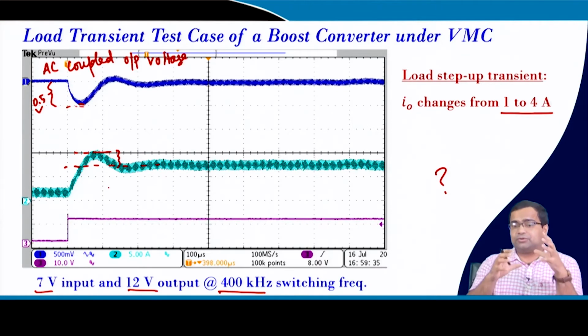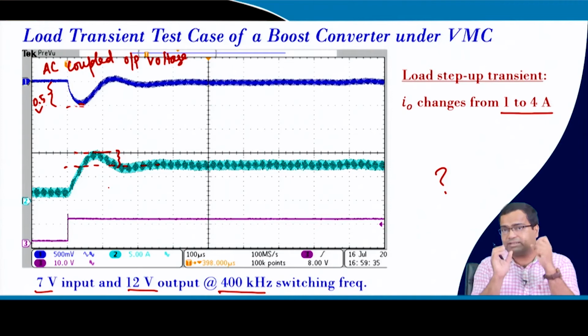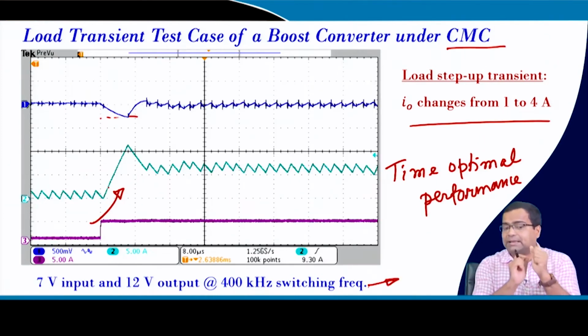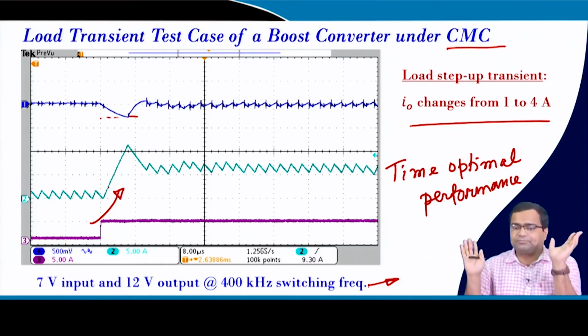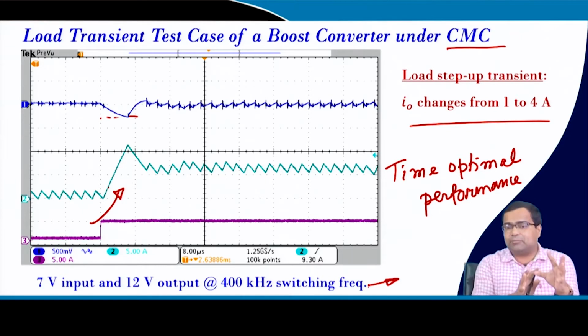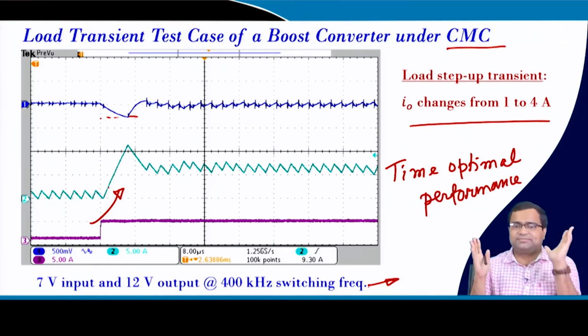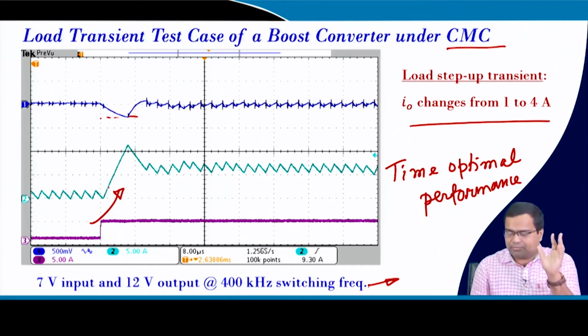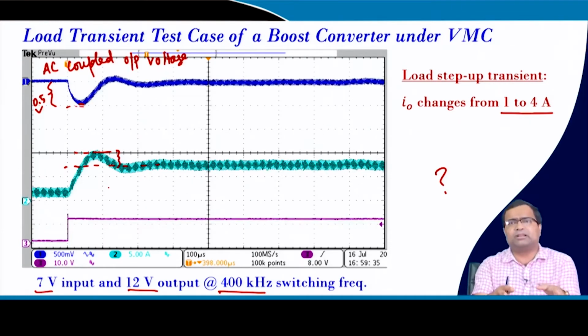In this approach, we will view the design of the controller using a transfer function, small signal model. And in this approach, your transfer function is not valid, as we will see, because we are allowing the duty ratio to saturate. So, your perturbation model is not valid because the perturbation is quite large and there is duty ratio saturation. That means the small signal model, even though we are familiar with it, is not applicable here. So, we need another level of modeling. Why? Because this model will turn out to be much simpler.